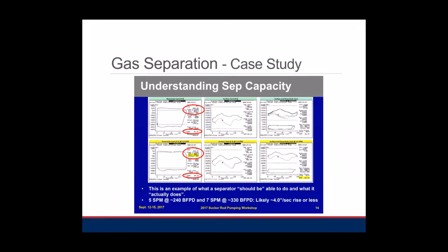So those were all laboratory studies, and if we take it out to the field, what we're looking at is a pump card. So we look at the top left. Essentially what we want to see, and this is simplifying it, is a square pump card. If it's not square, something's going on, maybe our rods are rubbing, maybe we're getting gas entrained.